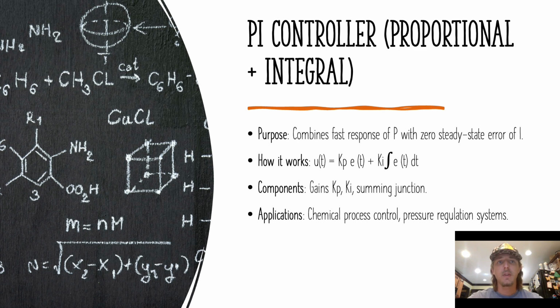The proportional (P) component reacts to the current error, delivering a control signal that is directly proportional to the size of the error. This offers immediate correction and helps the system respond quickly to changes and disturbances. However, a proportional controller alone often leaves a steady-state error, where the system's output hovers near but never really reaches the set goal. This is where the integral (I) component becomes essential. Combine these two, and it pretty much gets the job done.